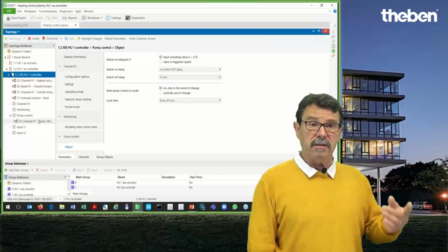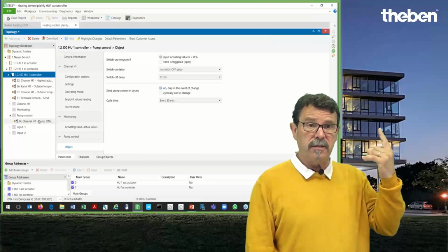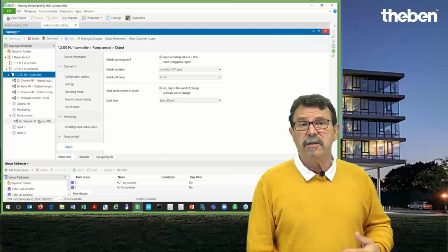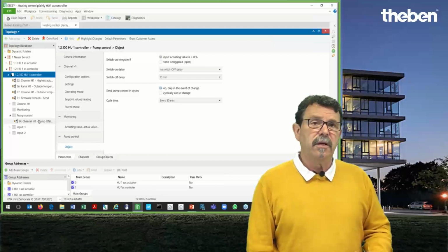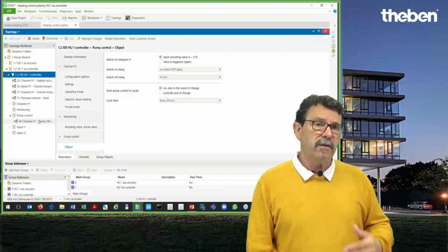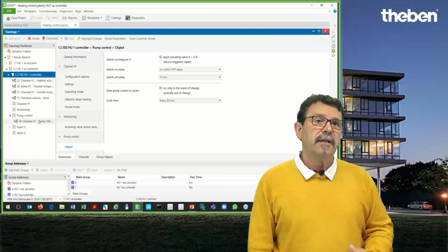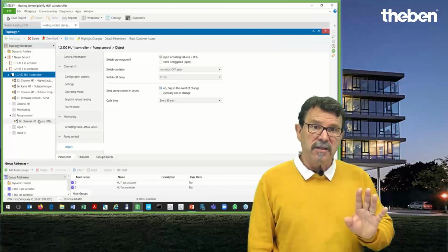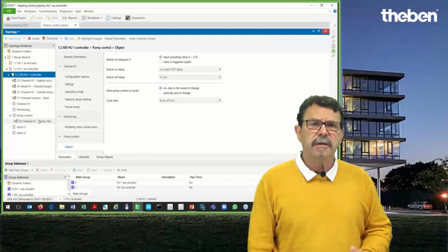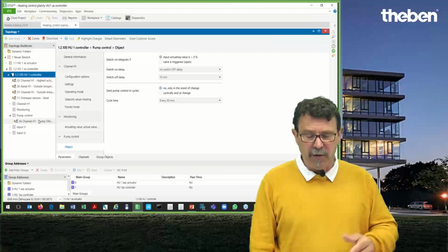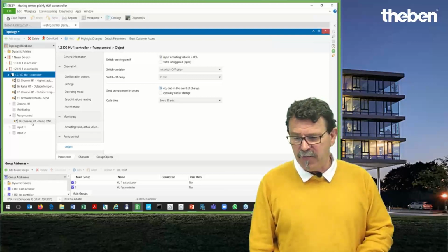If there is no demand in such a room, like here, for instance, lights are dark, nobody there, so why should the heating system be activated on this second floor, why should the heating pump move warm water into this entire circuit? Nevertheless, if the valves are closed or not, you can stop the pump as well and save additional energy on the heating pump side, if you want.